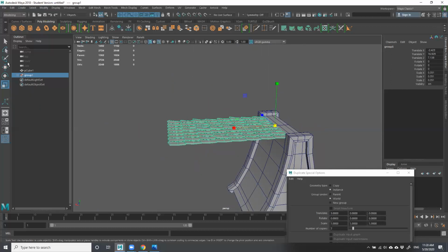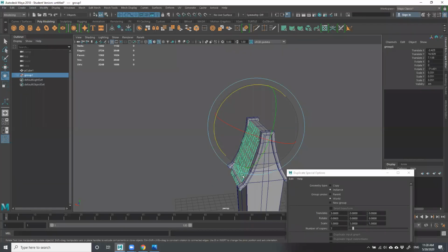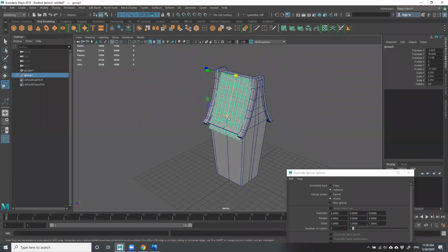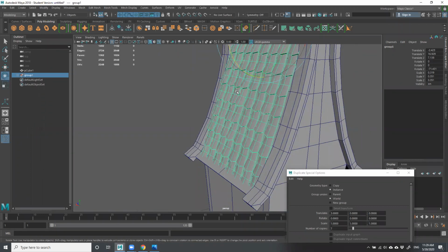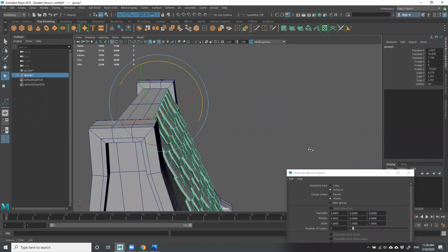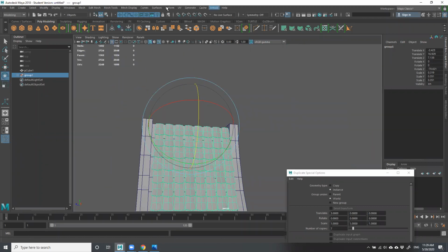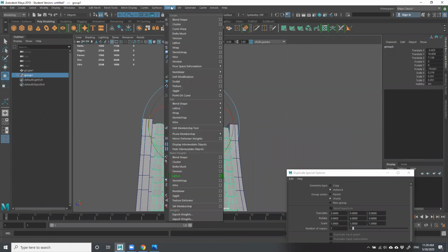And let's see what we get here. If I just place it in here, that's actually pretty cool. Let's see what we get here. If I do this. All right, yeah, that looks pretty good, except for the curve. And here's what I'm going to do with the curve. I like this right about there. Now what I can do here is apply a deformer. On the top menu it says deform. Here where it says nonlinear, I'm going to go to where it says bend, right?